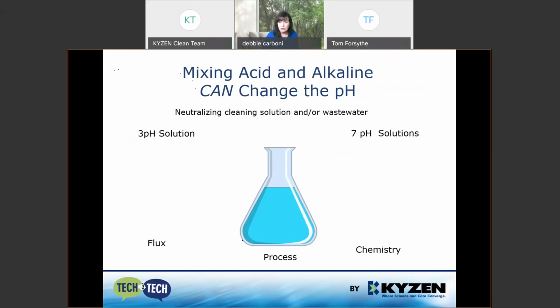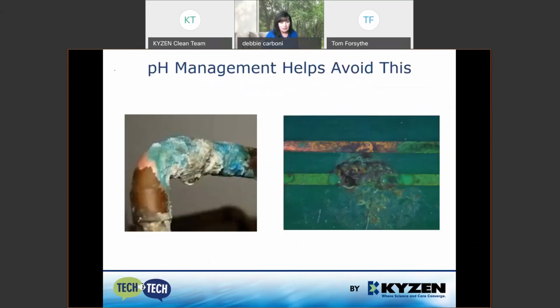If the pH of your cleaning product shifts a lot, regardless of where it starts, you can expect cleaning performance to decline, and to decline very fast. That means trouble in your production, which is never a good thing. Like we discussed, success is in pH management. It is critical to keep a stable pH when mixing the flux and the cleaning chemistry. Without the pH management, there is a risk of corrosion or harm to products, surfaces, or people. A major shift can cause major reliability issues.